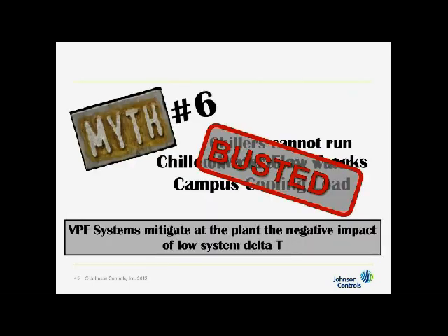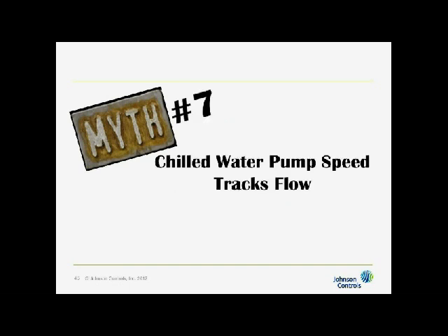Okay, so myth number 6, once again, is busted. Even with VPF systems, flow does not track load, but the negative impact of it can be reduced in the plant. Okay, myth number 7: chilled water pump speed tracks flow. A moment ago we said flow doesn't track load. Now we have a new myth that speed tracks flow.